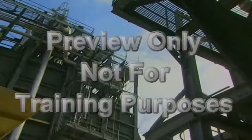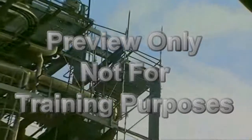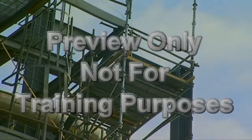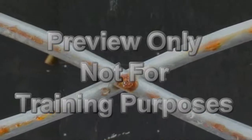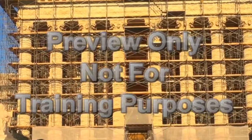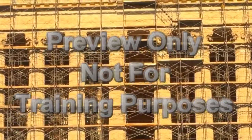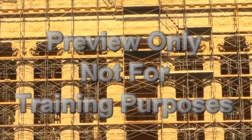Scaffolds must remain upright to be safe and useful. As a general rule, a scaffold becomes inherently unstable once its height is 4 times its minimum base dimension. Weather and damage to structural components can also affect the stability of a scaffold. When a scaffold reaches a height that is more than 4 times its minimum base dimension, it must be restrained by guys, ties, or braces to prevent it from tipping.